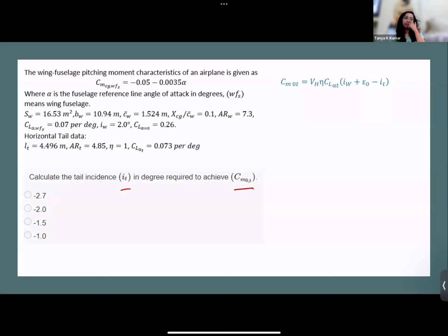Yeah, okay. Somebody had asked me about leading edge vortices in the previous session. So what I was able to understand, one of the instances where leading edge vortices are created, that was the question. So let me just draw it here. So what are vortices? When there's a boundary layer separation, it usually happens somewhere here, right? So when the angle of attack increases, the boundary layer separates, and there is vortex formation here. Now, what is a leading edge vortex? These vortices are formed at the leading edge. Why are they formed at the leading edge? There's a boundary layer separation at the leading edge.